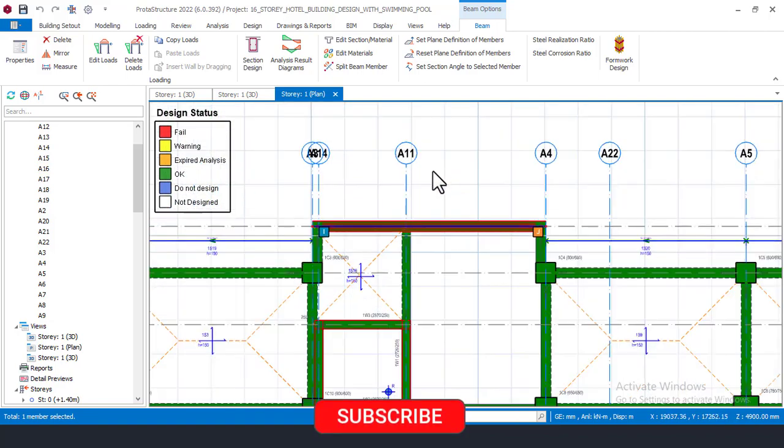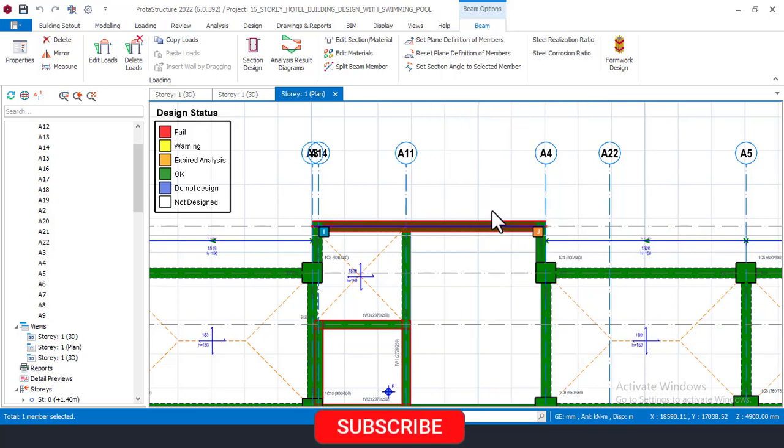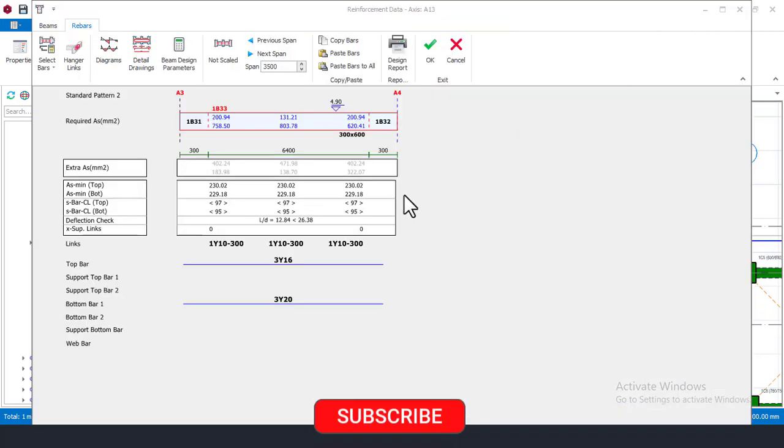So I'll right click on this beam, right click here, and then click on section design, and the beam property tab is now open. Once it opens, we will begin to check the reason why the beam is failing. As you can see, this is now the beam reinforcement dialog box. Here, the top reinforcement is 3Y16, and we have 3Y20 at the bottom, and for the links we have Y10 at 300 spacing. Okay, that's fine.